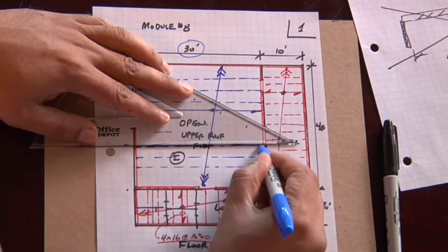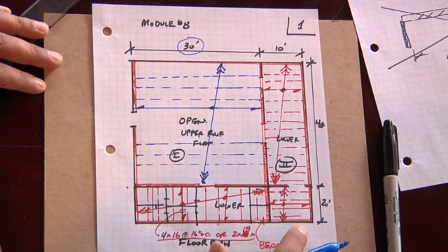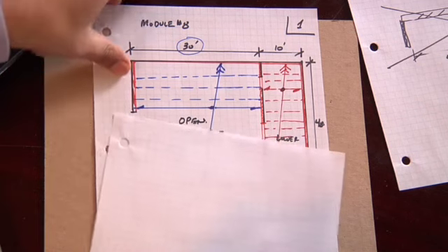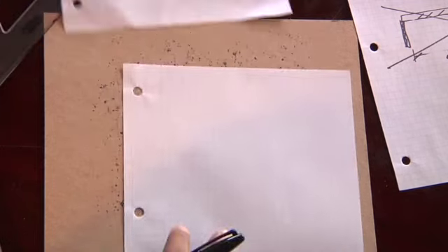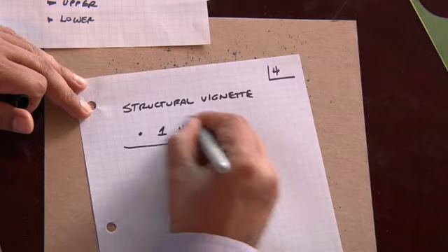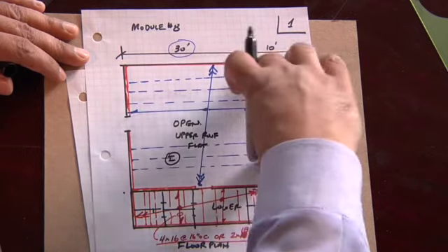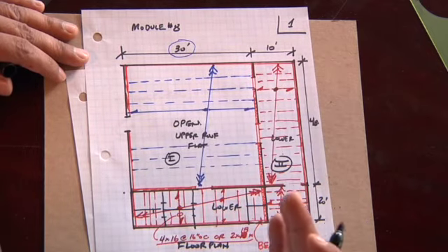So I don't see this as a very complicated problem. I think that you could solve this fairly quickly. And structural vignettes are really not that difficult to solve, but people tend to get caught up on them. You know how much time they give you on the test for a problem like this? They give you 1 hour. That's a lot of time. You should have no trouble laying this out in 1 hour. And so where people make mistakes is if they run the joists in obviously the wrong direction, and they do what I think is just a basic judgment error.